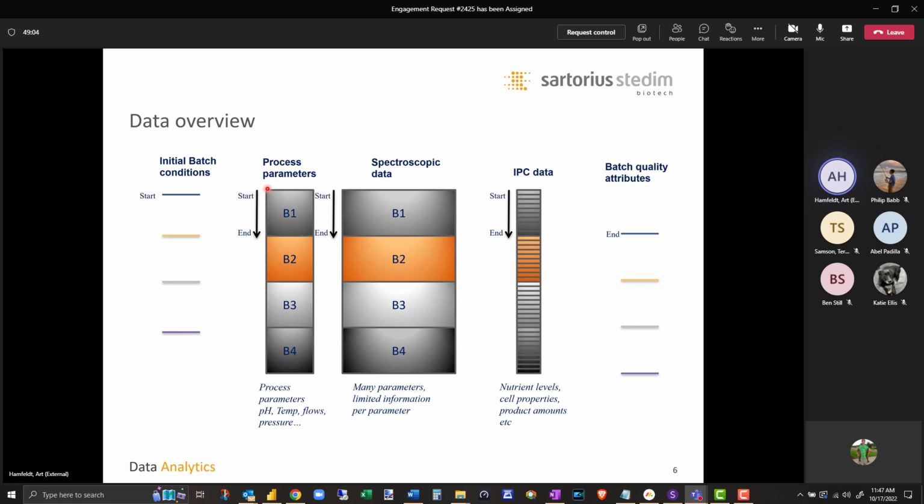Then we start the process. This is your runtime data or real-time data, right? So I have my timestamps come through here. Those are all my process parameters. I can then tie it up with my spectroscopy data. And I could tie this up here with, every four hours I pull off whatever I need. So this could be your K values you get off your roller. This would be the actual roller itself, right? That machine, this would be your K values. And this could be the laboratory confirmation of whatever, fiber length or something like that, right? So all these can then be pulled together. You can start to see they have different timestamps with each of these.